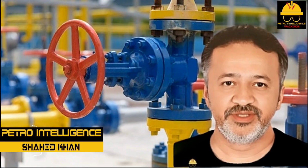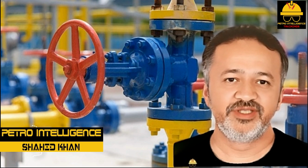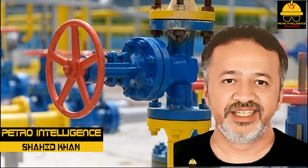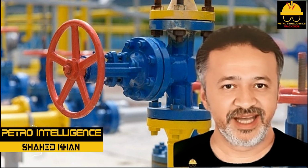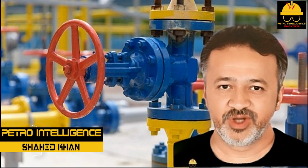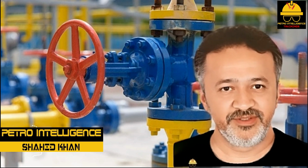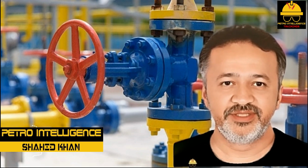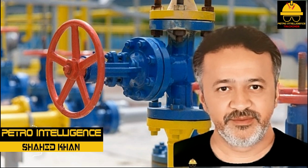Globe valve materials. Globe valves are designed to be used in a variety of process conditions. The specific condition dictates the type of material the valve will be made of. For example, the stainless steel globe valve is used in corrosive, high and low temperature services. The specialty alloy globe valve is used in high temperature and high pressure services. Some common alloys used are nickel and iron or steel and titanium.